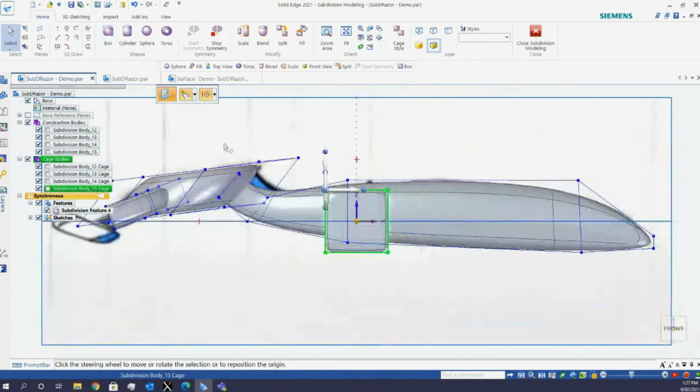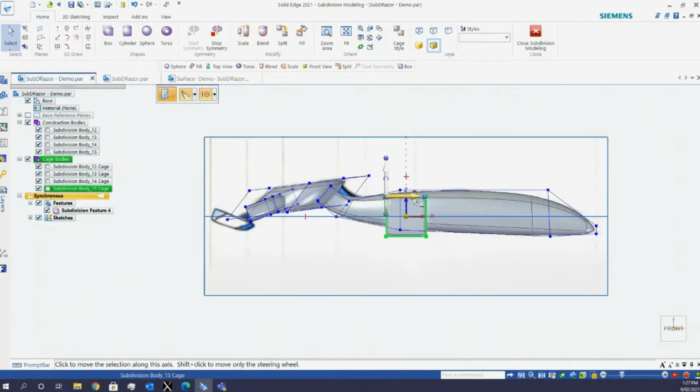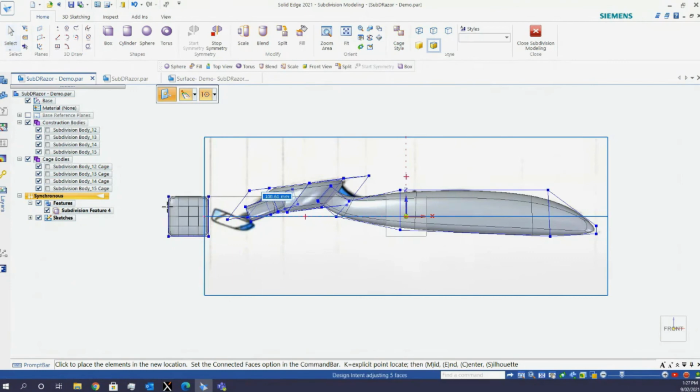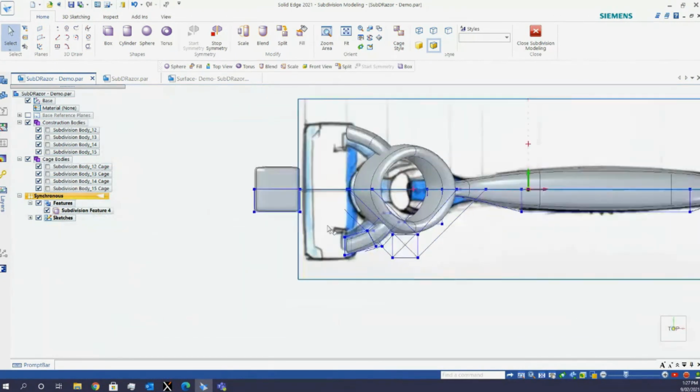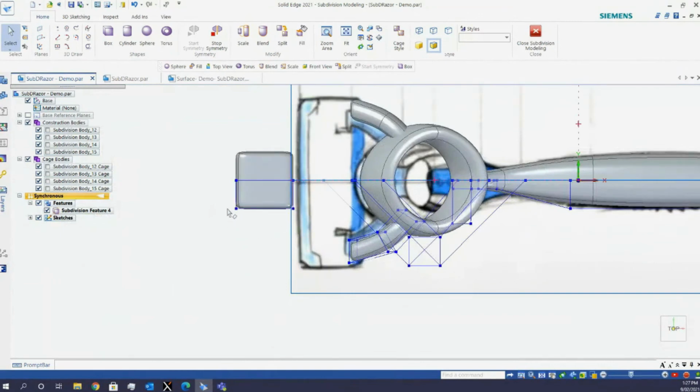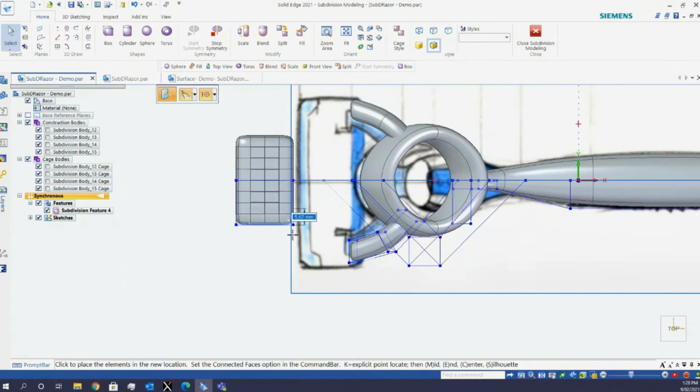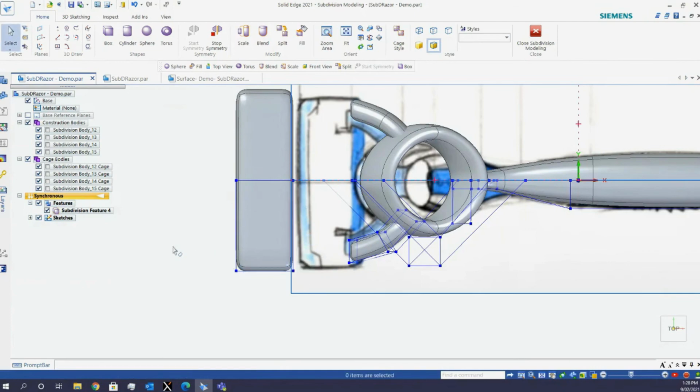You can see my box added in here. Gonna move it a bit even further outside to compare it with my blended top, this face here. So let's look at it from the top face. Again, rather than selecting the faces, I will select the edges in subdivision modeling, and basically I just drag it down to get roughly the size I want.